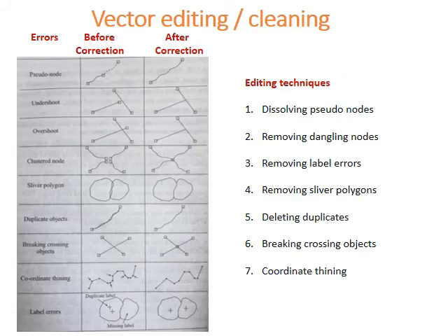Now once you verify and check your vector data entry and identify the errors, it usually requires editing to remove the errors for further processing. We can correct inaccurately drawn data or inaccuracies resulting from surveying, digitizing, or scanning processes. We can also apply a simplified methodology in order to align the map correctly or obtain answers to questions such as is the data complete, or are there any duplicates available, so that you can edit your data or clean your data before your analysis.